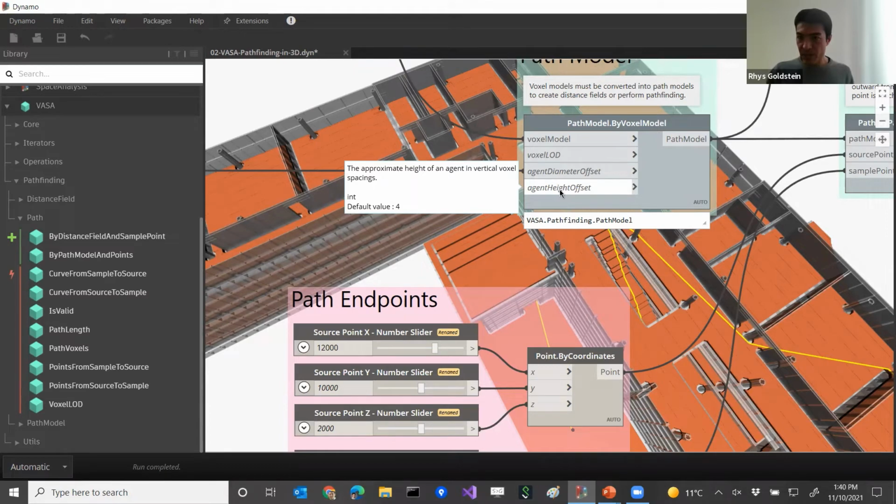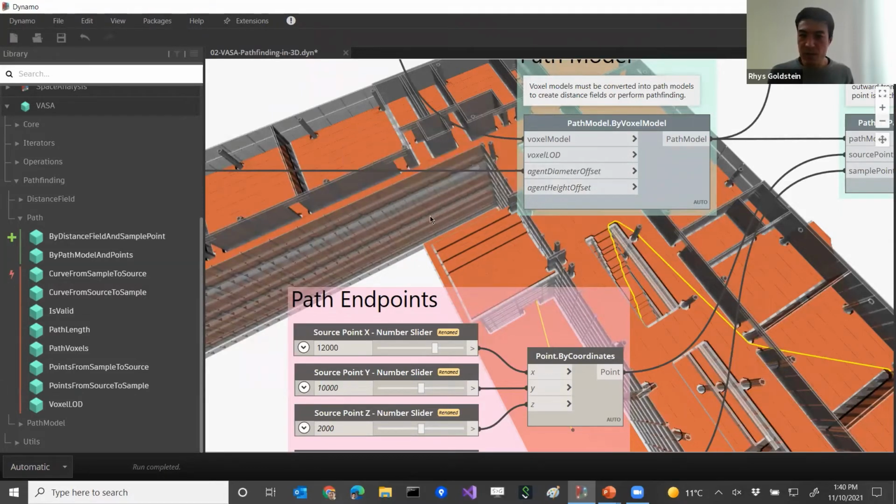If you have a door that's 2 meters tall, just for example, the bottom of the door when you voxelize it could come up by about as much as a voxel, which is 25 centimeters, and then the top could come down by 25 centimeters as well. So that 2 meter opening could become a 1.5 meter opening. So to be safe, we choose a height that's quite low by default, 1 meter. If you make it too small, then you'll be able to walk under tables.